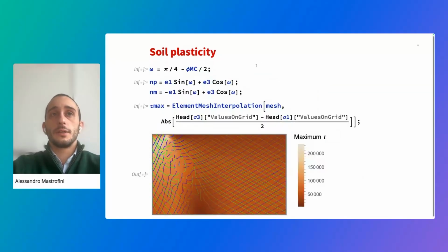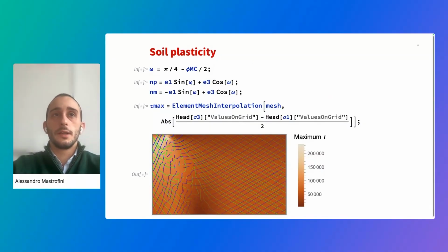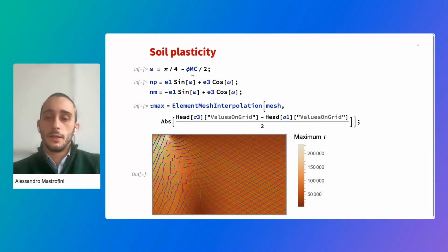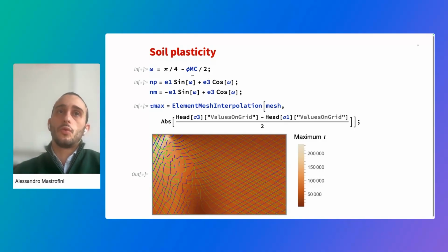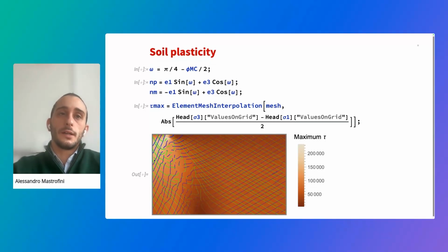And it's also interesting to extract the failure lines, which are lines connecting the first principal and the last principal stress direction. Generally, depending on the criterion, but for the Mohr-Coulomb, you have this Mohr-Coulomb angle, which gives you a factor to modulate this line. And what we can see is that the lines show where the material is going to fail, and also how the material is going to fail.